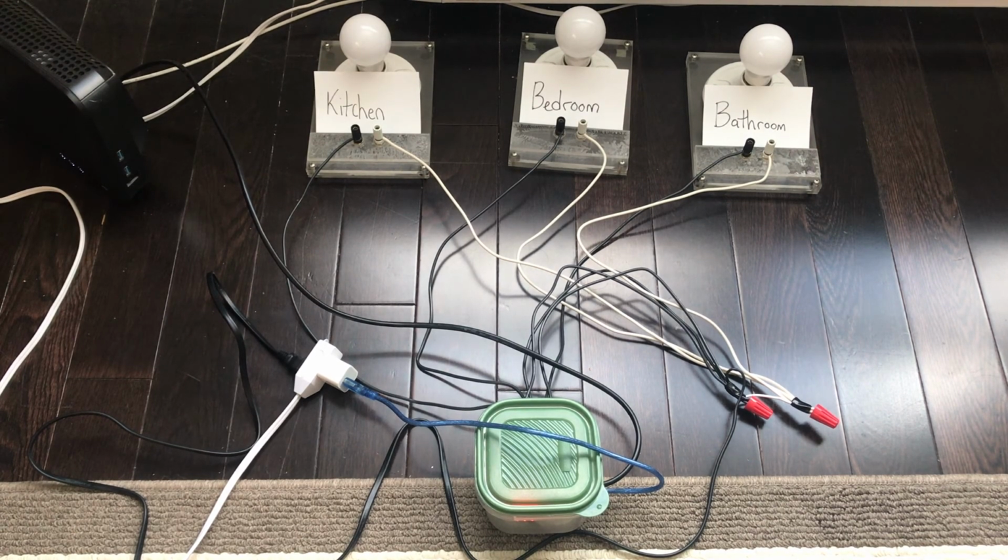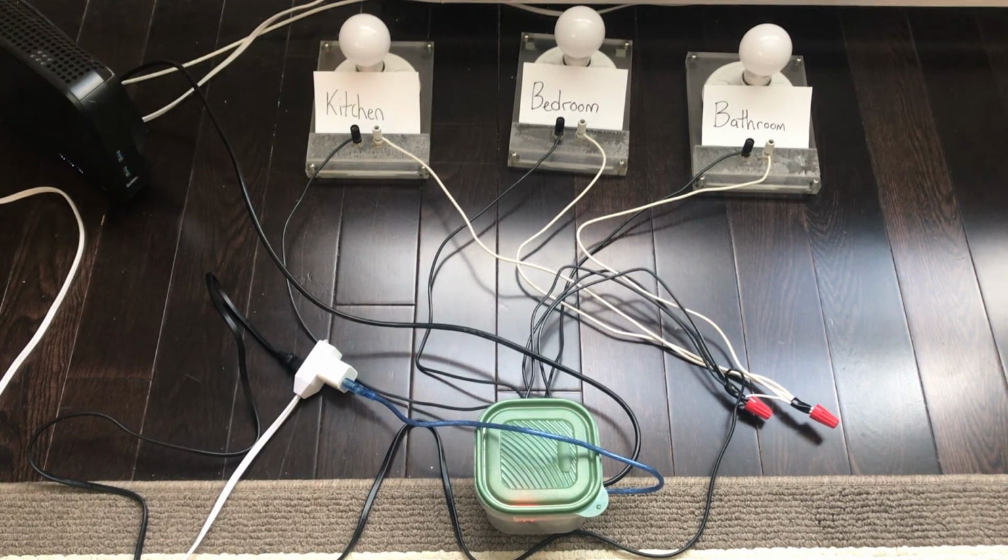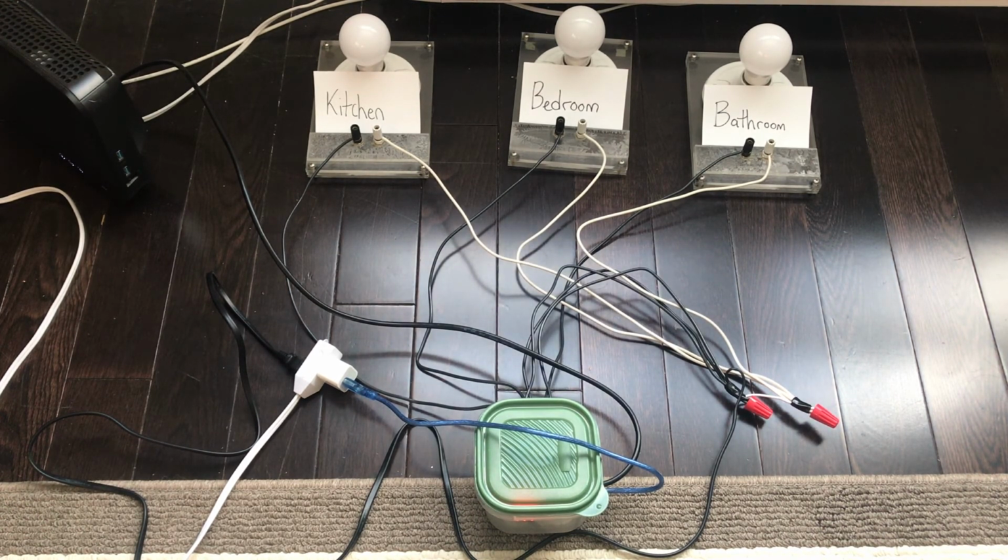It is important to note that when an input of 0 is sent from the Arduino, the relay circuit is closed, meaning that the light would turn on. Therefore, it is necessary to wire the relays in normally closed and not normally open configuration to account for this discrepancy and get the desired output instead of the inverse.